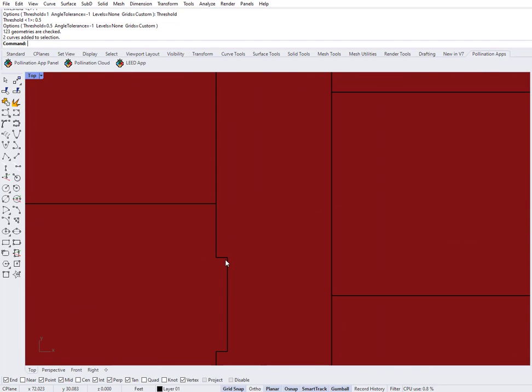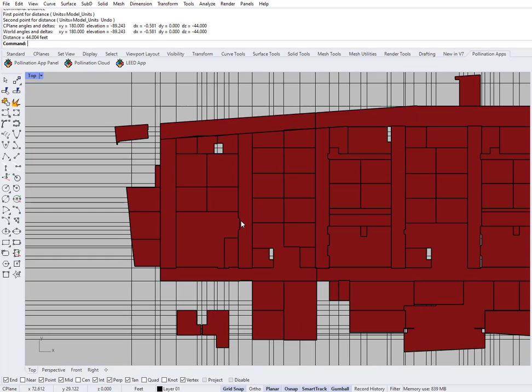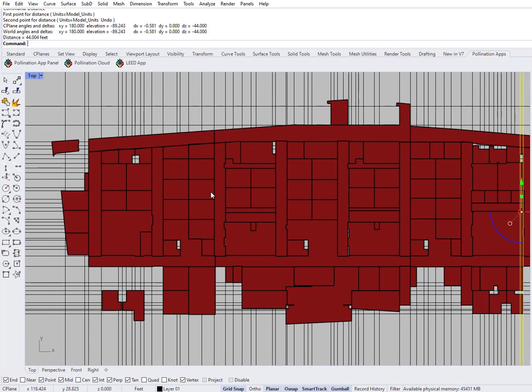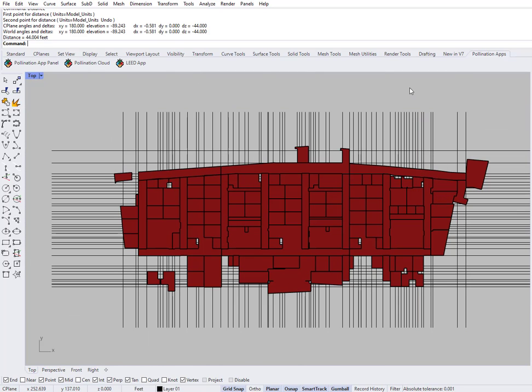This is also here because of the tolerance that I put. So if I had a higher tolerance, then I wouldn't see this. This one is 0.58, so it was a little bit more than 0.5. So maybe if I wanted to get all of this fixed, I could have run the command with a higher number, maybe I can set the threshold to 1. So that's a better input. So let's rerun the command.